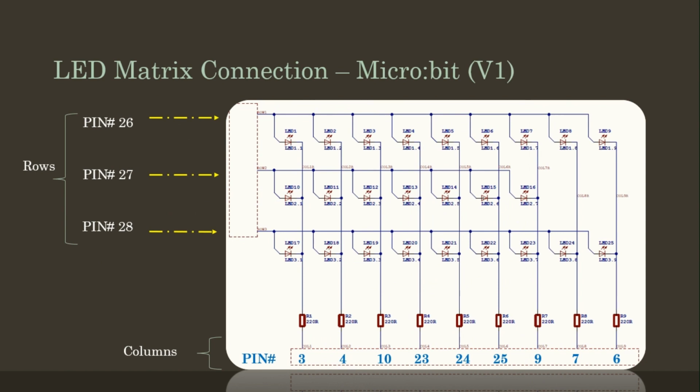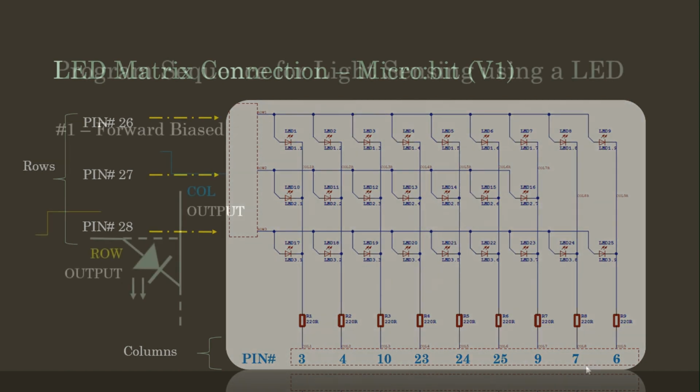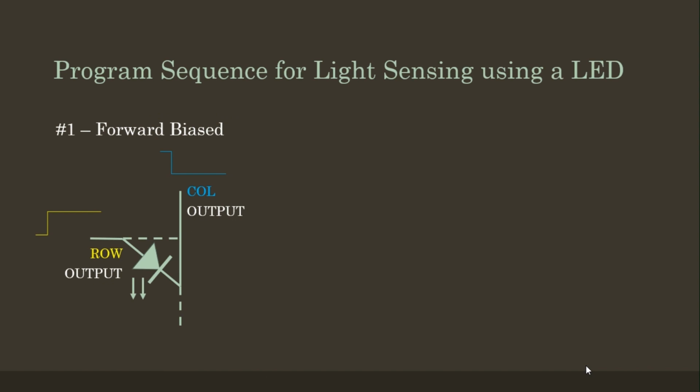When the port pins connected to the LEDs are set as output, the default state of the output pins is low. You need to keep these things in mind while developing your program. The program sequence could be like shown here.